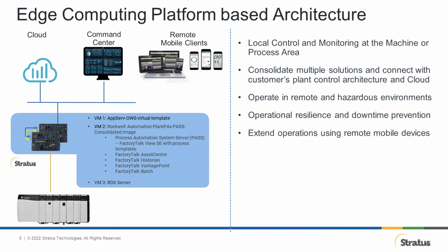The second key capability is operational resilience, and they have three big advantages. First, edge computing platforms with operational resilience come with built-in redundancy that prevents unplanned downtime from happening. They are ruggedized, where you can install them in harsh environments and in some cases come in Class 1 Division 2 certified. These edge devices you can install in a control panel together with your PLCs, your drives, and other control equipment. And lastly, it is a platform that can help secure your control infrastructure from cyber attack.